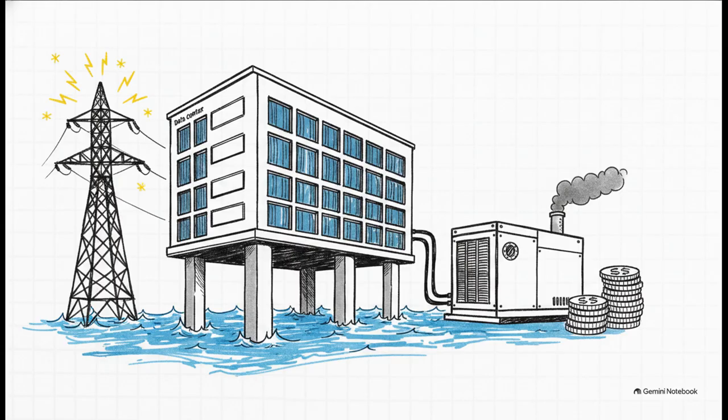Second, grid voltage fluctuations mandate extremely robust generator backups. On top of that, the Bangladesh Bank is actively driving Tier 3 standards for compliance. And because of high urban density, retrofits heavily dominate over new greenfield builds. Look, in Bangladesh, grid instability means those N+1 diesel generators aren't just backups sitting there for an emergency. They are everyday necessities, which obviously drives up both your capital costs and environmental emissions.